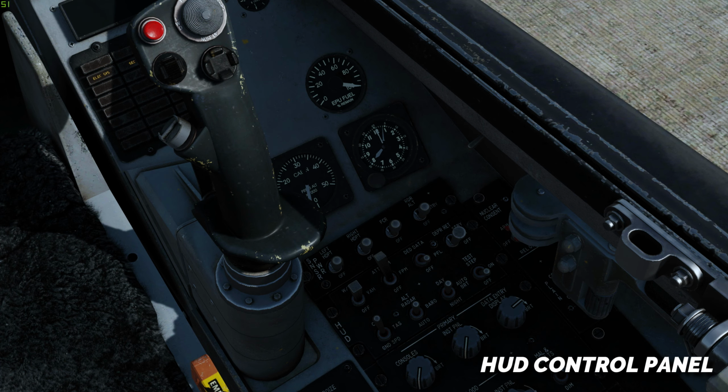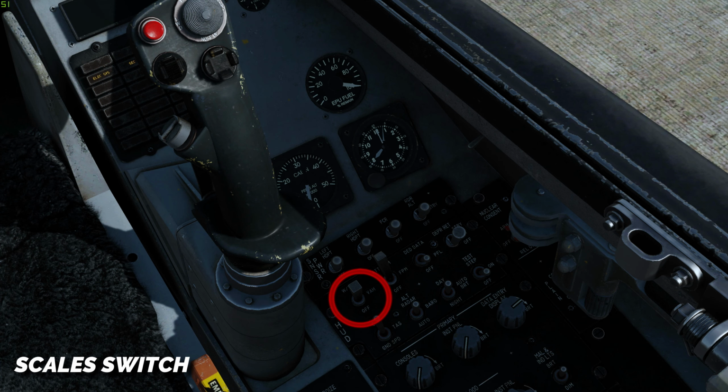Set the HUD control panel. In the VV/VAH position, vertical velocity, altitude and heading are displayed on the HUD. Vertical velocity is displayed inboard of the altitude tape and is marked at 500 feet intervals with a caret, indicating the velocity vector. A roll indicator is displayed above the